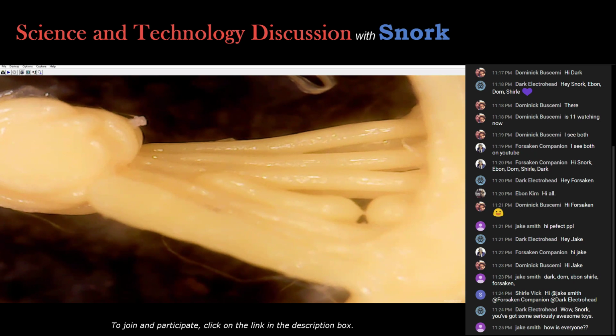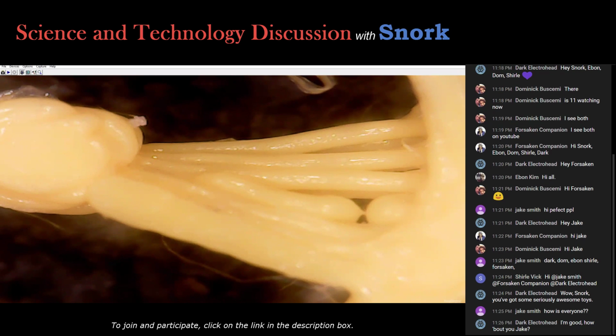Another method is to take a powder and fire a laser at the powder, and on each layer, draw what that layer should be. So you melt the plastic, or even the metal, into the layer it's supposed to be. So your 3D print is actually a whole bunch of slices on top of each other. And the program that turns your shape into the individual slices is actually called the slicer.